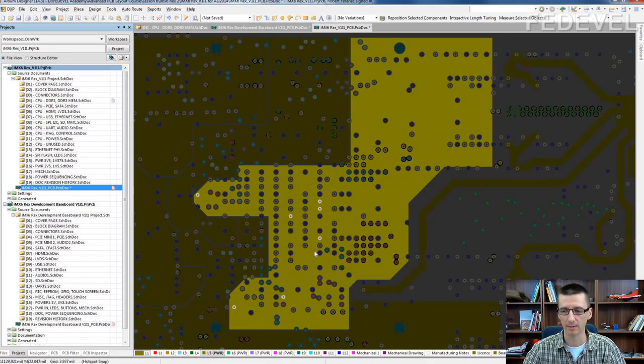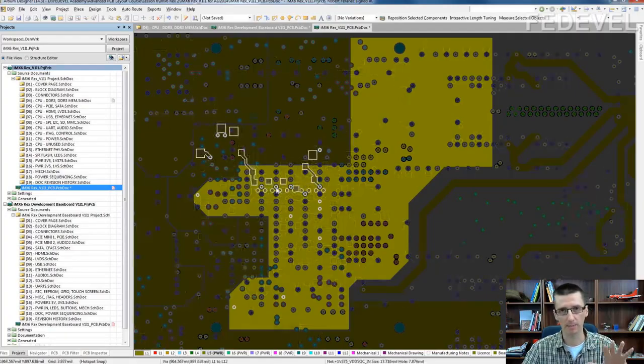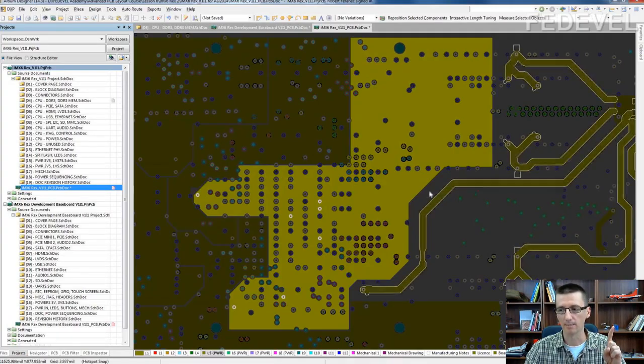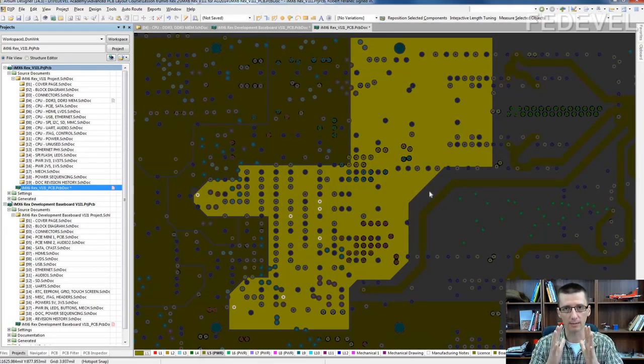This is the case. And the bigger the area where the ground and power plane are together, the better the filtering. So always in my designs, when I have a high current power plane and there is some free space on this layer, I try to make it as big as possible. But the neighbor layer has to be the ground plane, and these planes need to be inside the PCB. I do not draw huge polygons or huge planes on the top or bottom layer.